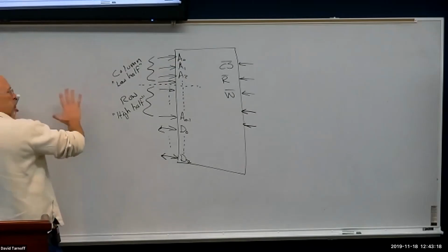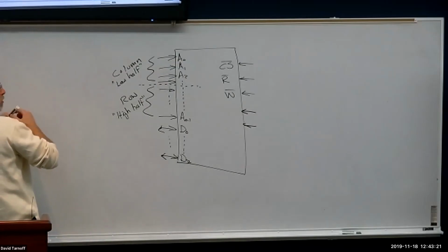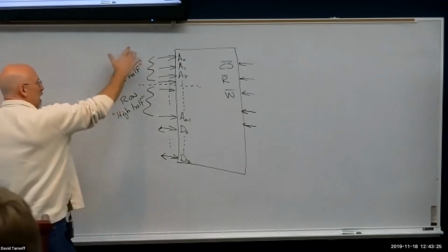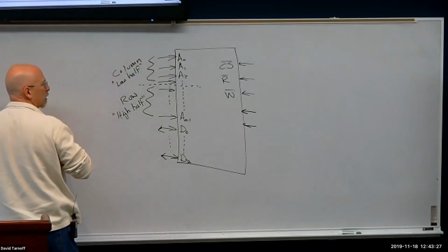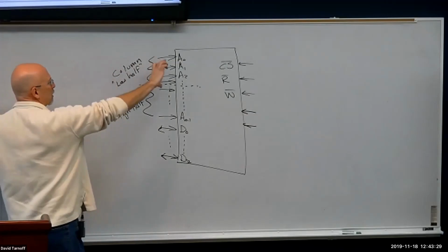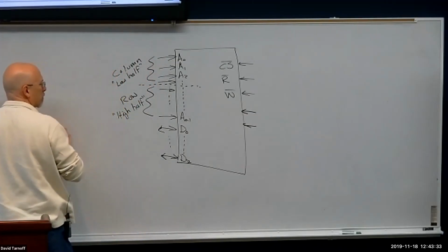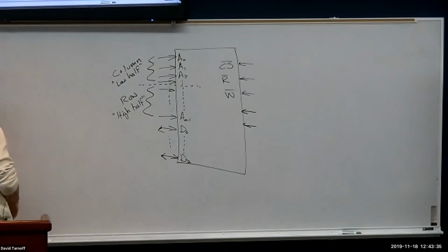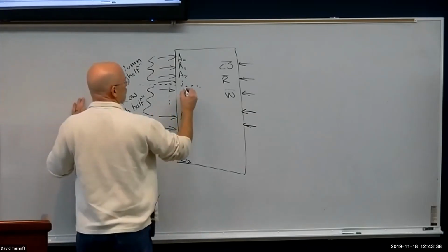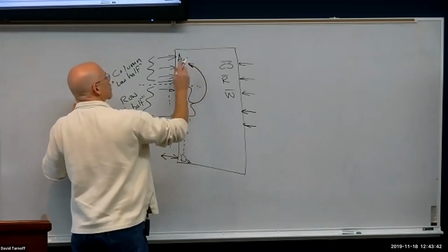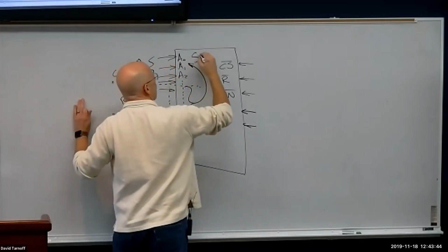And when you look at what's coming from the processor, the interface to the memory, there's actually only one set of connections, one set of pins that are shared for both the row and the column. And so in essence, these upper bits of the row actually map to the same physical pins.